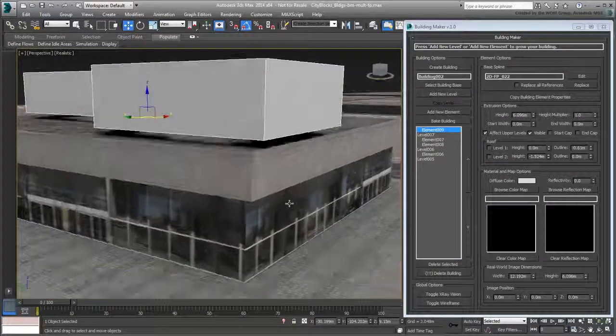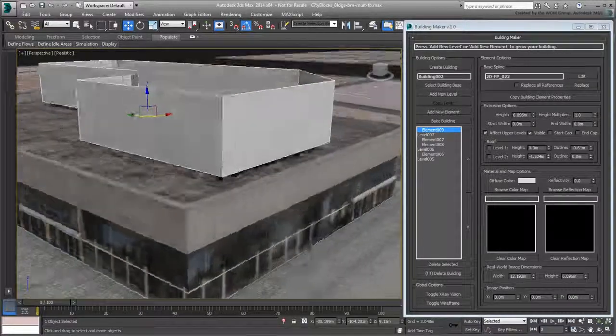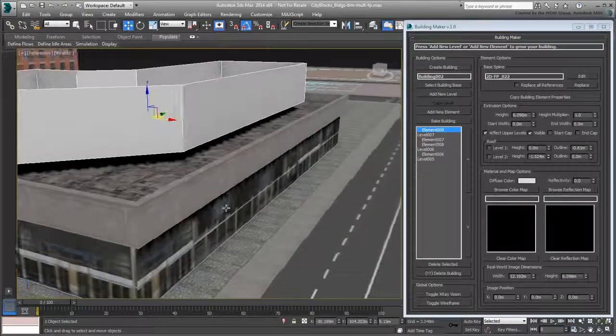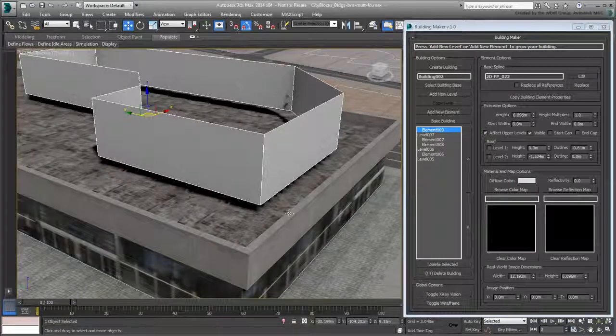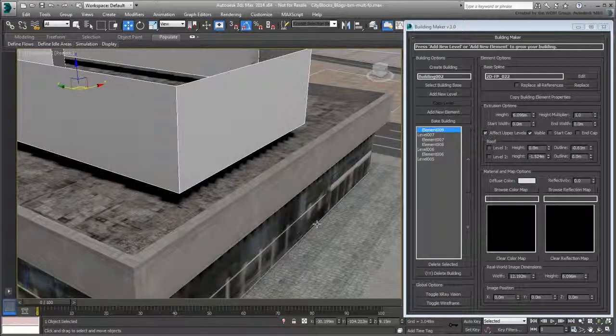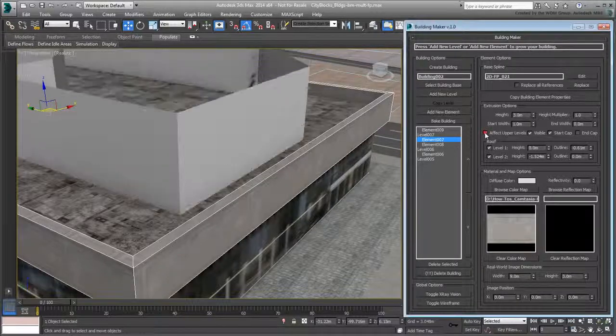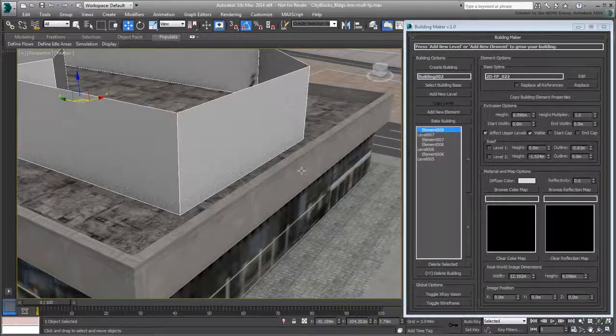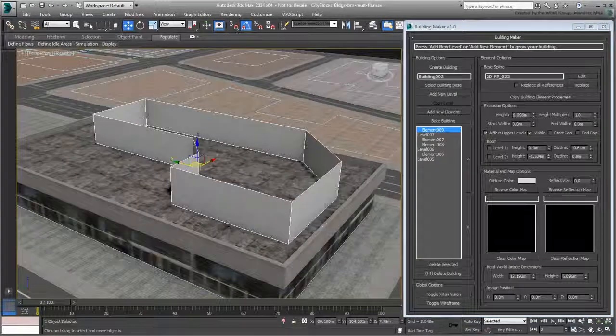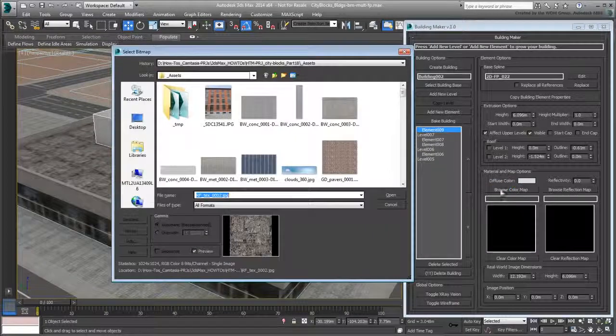This is because of how Building Maker treats building elements. It is based on a hierarchy of levels, where the position of every floor element is based on the level below it. In this case, the bottom part of the tower is dependent on the upper part of the parapet. However, you can select an element, like the parapet in this case, and force it to disregard any upper floors. This makes the upper floors look for the next constraint in the hierarchy, which in this case is the gravel surface. Once that's done, all you need to do is define and adjust the tower's parameters.